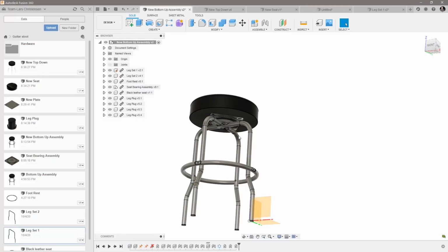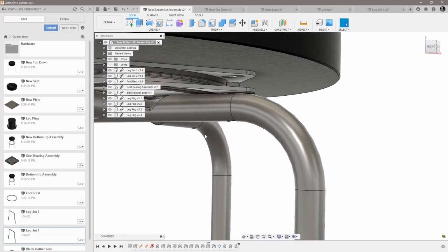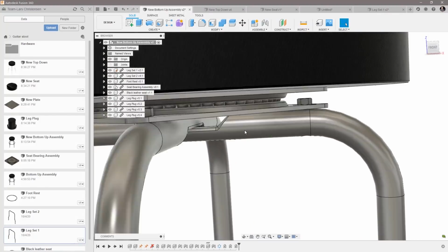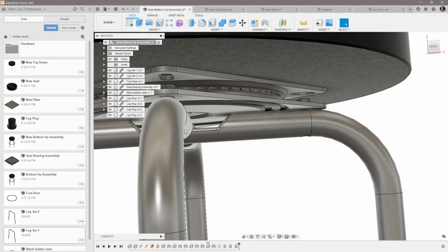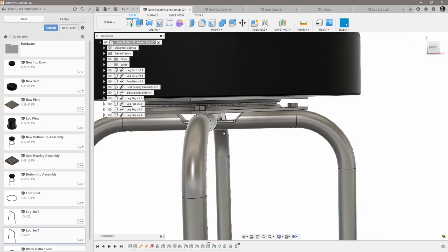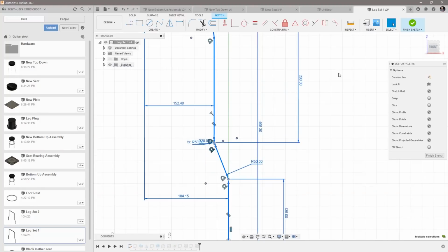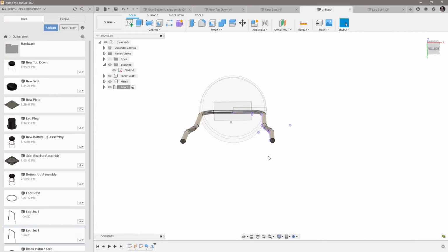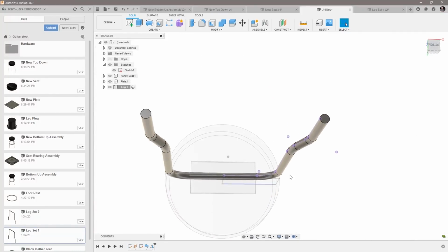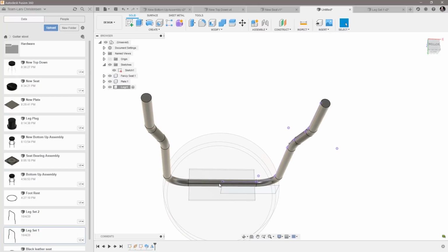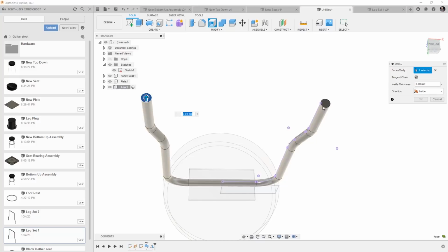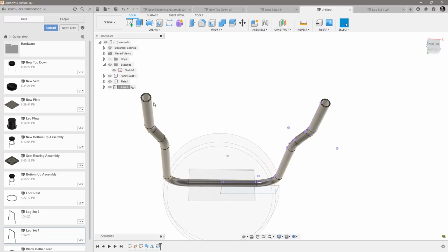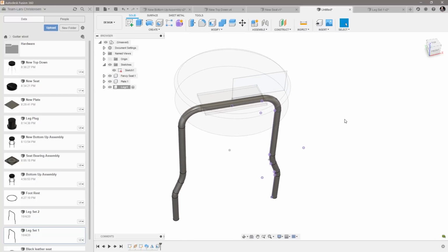And in our original file, you saw that I made that with cutout. It doesn't look very pressed down. But I wanted this to be a tube. So what I did in the end with the compressed in there was that I just shelled it out by clicking here and make it 2 millimeters shelled. And now it's a shell thing.